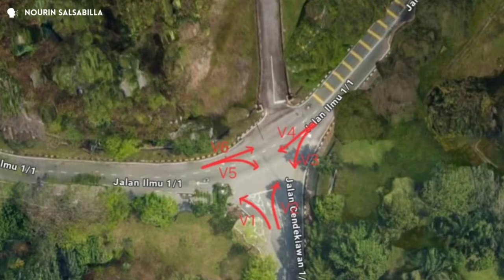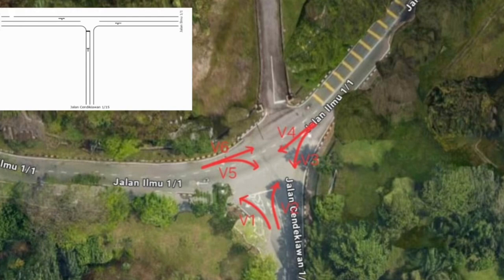From junction capacity analysis, we found that this is a two-way stop control intersection, where the minor road is from Jalan Cendekiawan 1/15, while the major road is from east and west of Jalan Ilmu 1/1. We observed that there is moderate vehicle flow during peak hours and frequent stopping on the minor approach. Our team has collected data and analysed it using Sidra intersection software to evaluate performance and safety rates of the route.